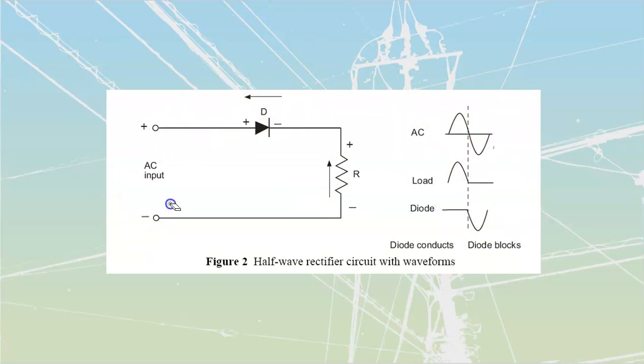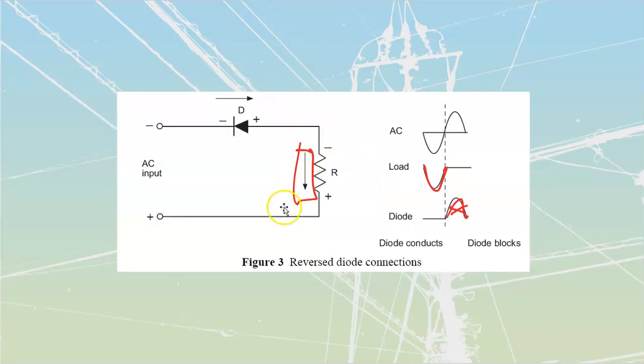It's going to be looking at that direction of polarity in the diode, and that's really going to redefine what I can place through my actual load itself as far as direction. Talking about values that we are going to have on here, peak and PIV are two that we need to know about. Peak value is obviously going to be the peak value of voltage that's going to get passed through to this load over here.